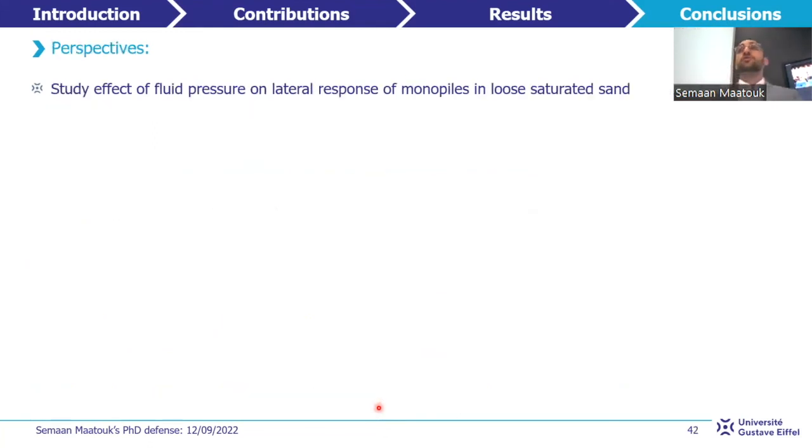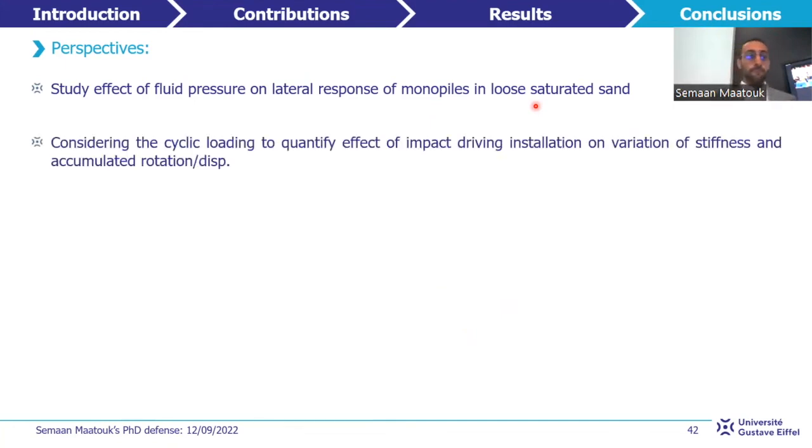As a recommendation for future works, it must also study the horizontal response of the monopile in looser saturated sand, and conduct a parametric study on the harmonic frequency and fluid viscosity, in order to study the effect of fluid viscosity on the behavior in question. Secondly, the offshore environment is cyclic in nature. Therefore, it would be interesting to quantify the effect of the impact driving installation on the variation of the foundation stiffness and accumulation of rotation displacement.